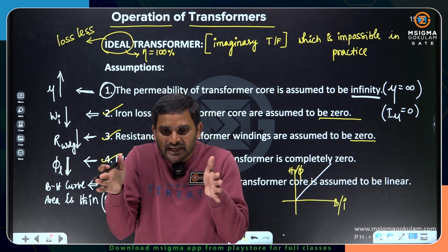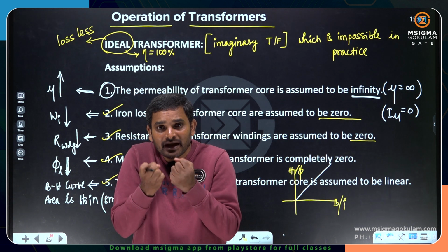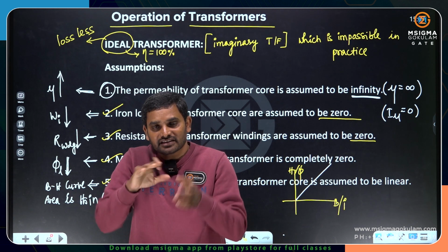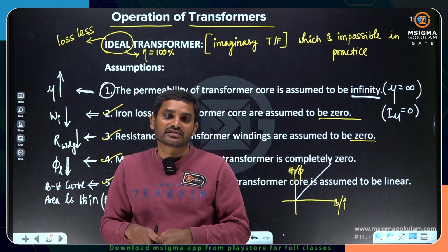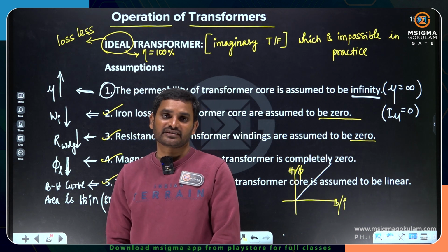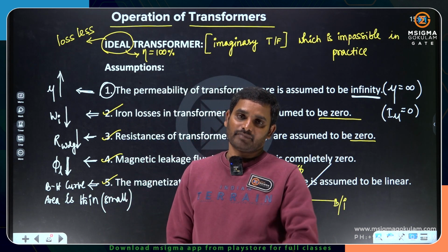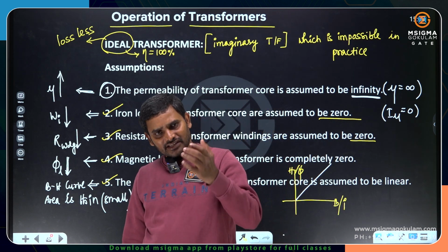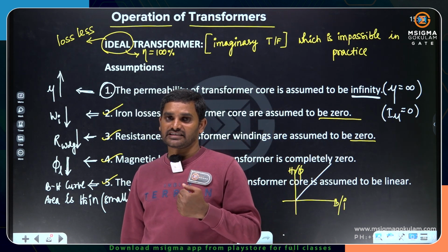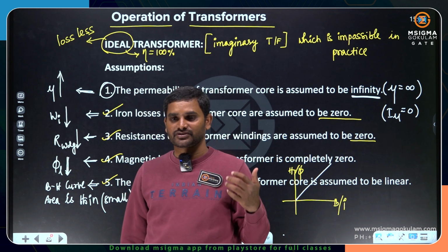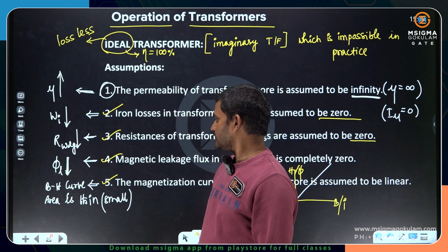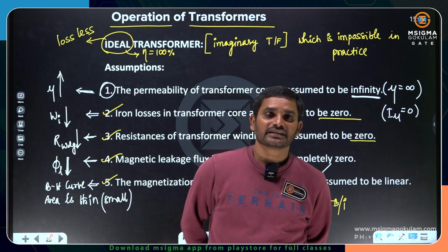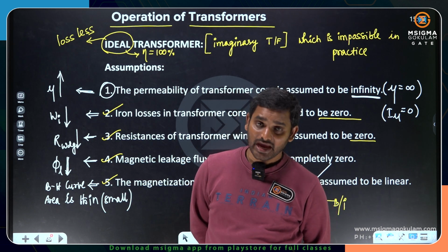If the area under the BH curve is small, the energy demanded by the core for the reversal of polarities will be less. Especially for reversal of the magnetic polarities, north pole, south pole, north pole, to reverse their polarity it will consume some amount of energy. That energy we call hysteresis loss. We will discuss it in the magnetization procedure. So here the area under the BH curve is going to be very small. You have to design like this.